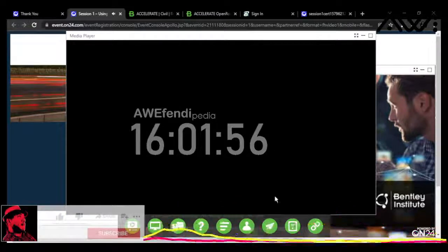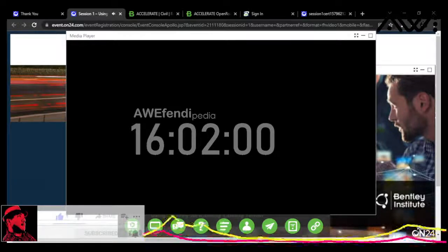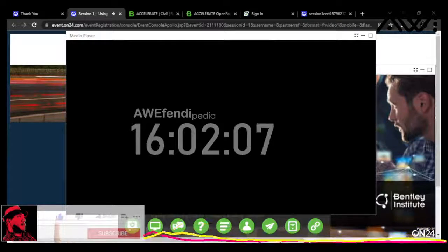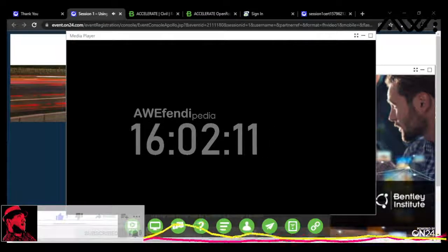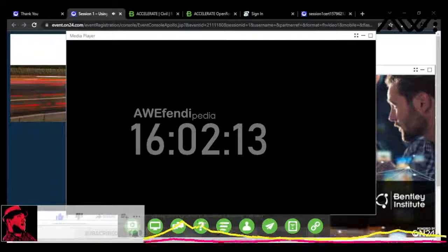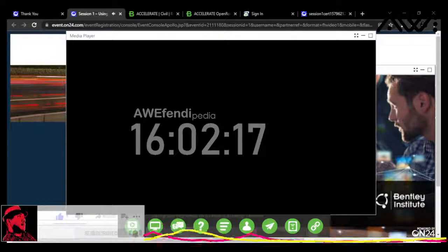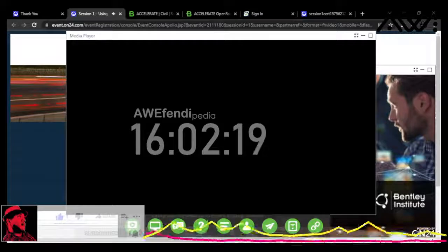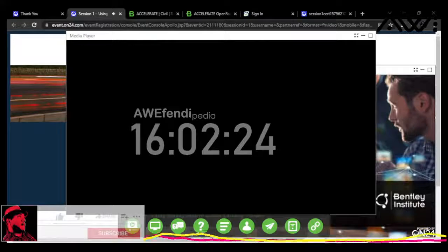There is an option if you are more used to working with just a point list feature. You can choose that to be forced on import. Now we're going to look at this a little later, and we're going to manually change some linking code features to point list features. But for right now, we're going to keep them all as linking code features. So a lot of the control of what's happening on the import from the raw data to the graphics is handled here in the linking code section.